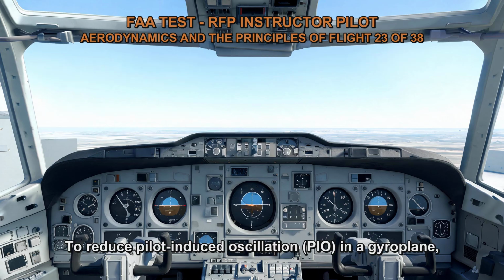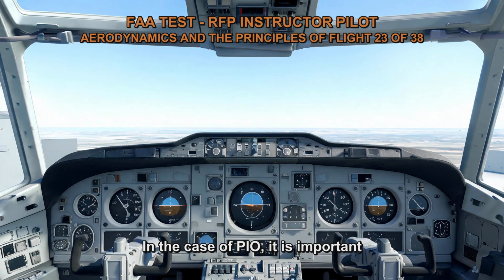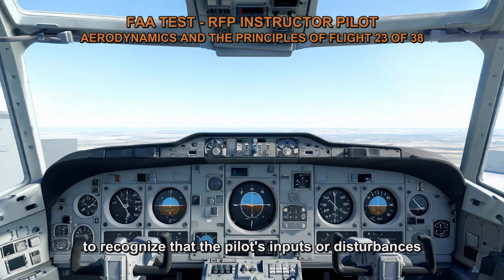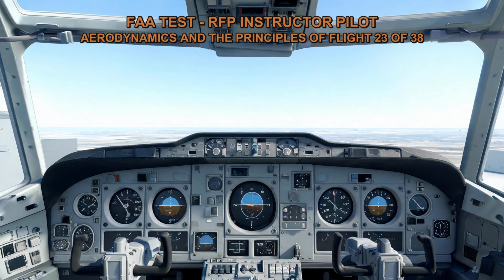To reduce pilot-induced oscillation, PIO, in a gyroplane, the pilot should take specific actions to stabilize the aircraft and prevent further oscillations. In the case of PIO, it is important to recognize that the pilot's inputs or disturbances are causing the oscillations. To mitigate this, the pilot should make appropriate adjustments to regain control and stabilize the aircraft. One effective action is to reduce power.